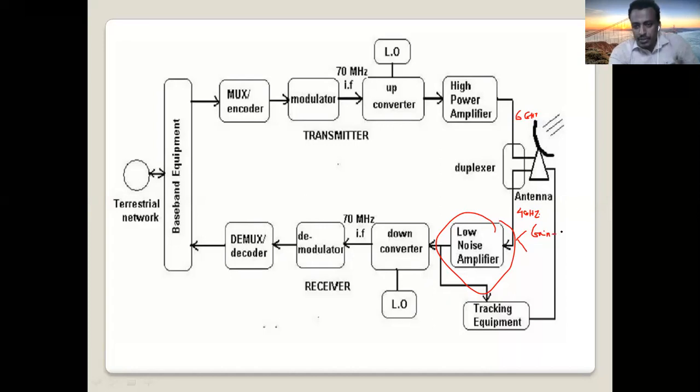Typical low noise amplifier we use in our satellite TVs. You can buy this low noise amplifier for around $8. Gain 60 dB, high gain, and the noise generated by this device is only 0.6 dB. But when the signal comes from the satellite side, our signal plus there will be what? There will be noise, right?